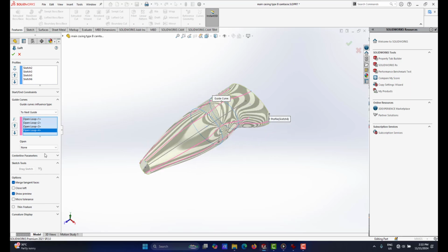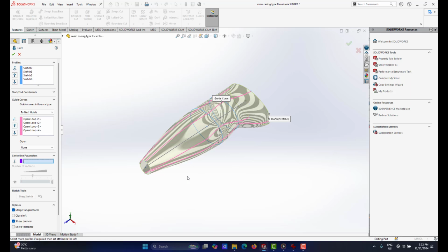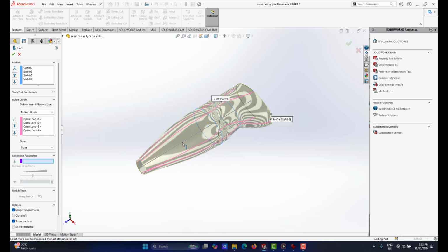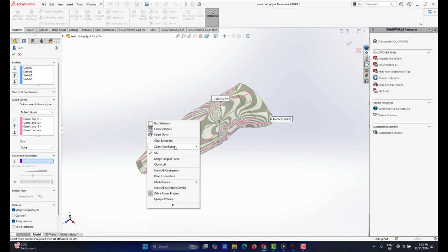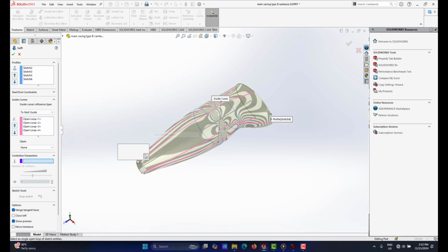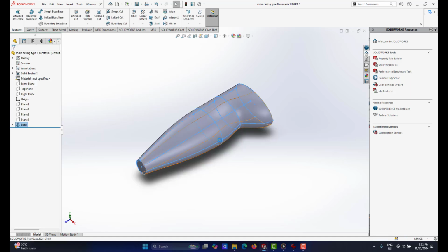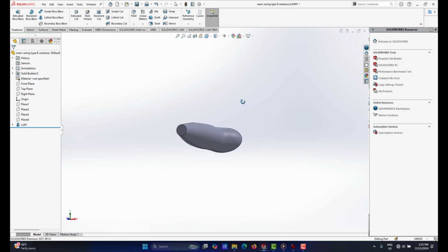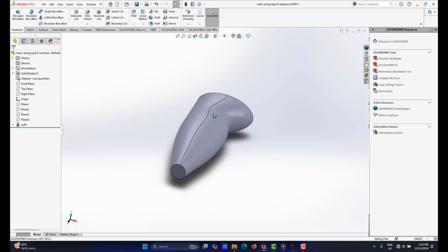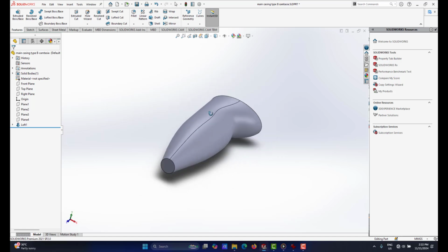All right. Okay, the last thing to do is the center line parameter here. So this is the center axis that we have created from the beginning. I've already changed it to solid line. When you make this one center line, it cannot detect it. So I will use selection manager, open curve, then I select this as my center line parameter. Okay, if I click OK, now I have the shape of this casing, of this organic shape of this milk frother casing.